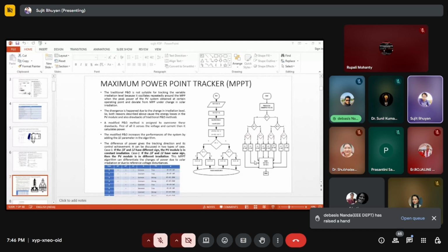See, here I have taken VA, VB, VC from the rotating axis to the direct and quadrature axis: the ABC to DQ converter. Here I have also used the PLL, the phase lock loop. The basic working of the PLL is to create the phase angle, which is used to give the reference to the ABC to DQ converter.